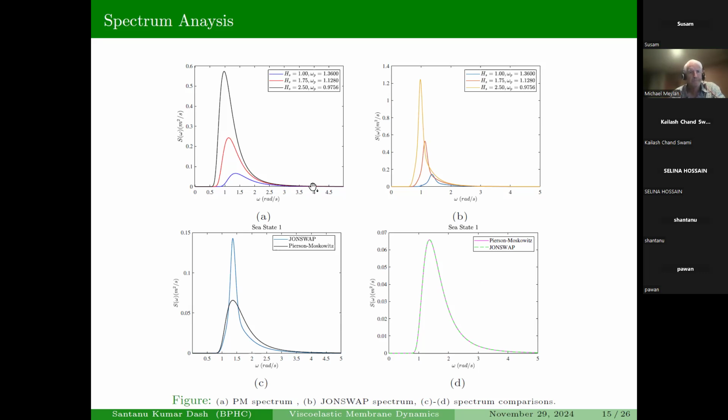We have considered three suitable sea states to represent this spectrum. To estimate the parameters, we plot the spectrum first and find the cutoff range where the entire energy is well distributed. In this figure, between 0.5 and 3 the energy is distributed very nicely.